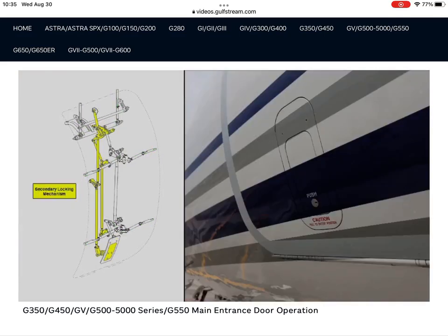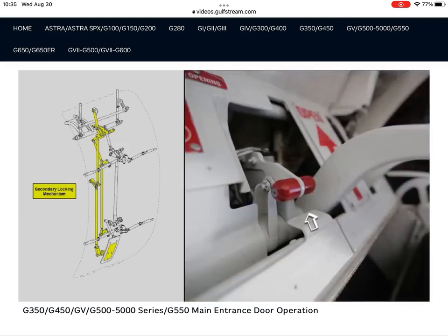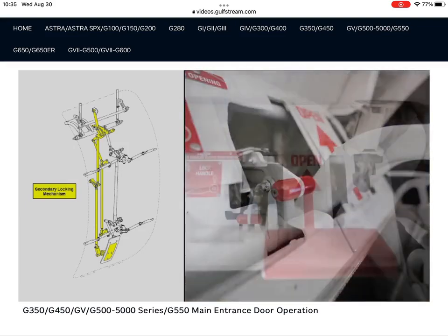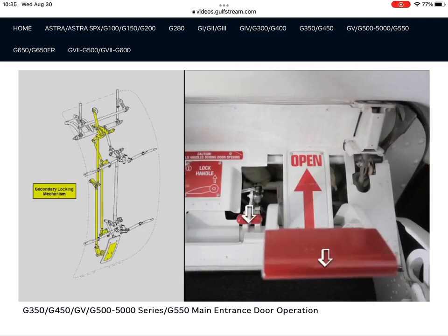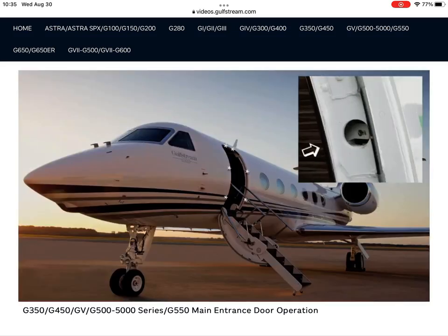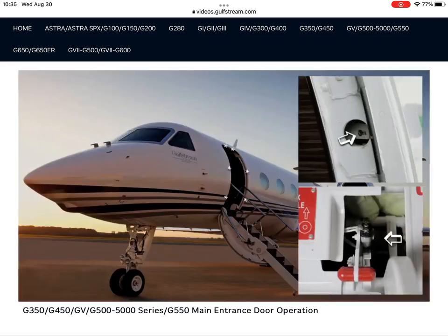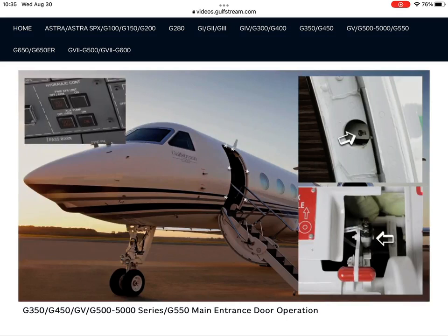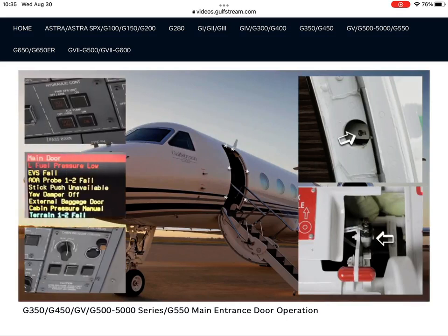The secondary locking mechanism is operated by depressing the inner paddle on the outside of the door or lifting the small aft handle on the inside. The secondary locking mechanism secures the primary locking mechanism in the closed and latched position or the open and unlatched position. Micro switches activated by the bayonets and secondary locking handle control the auxiliary pump, door warning, and pressurization systems.